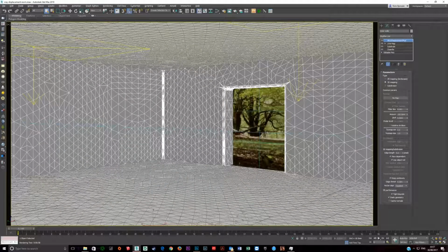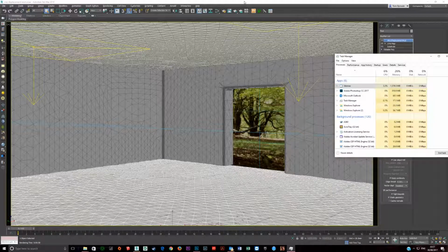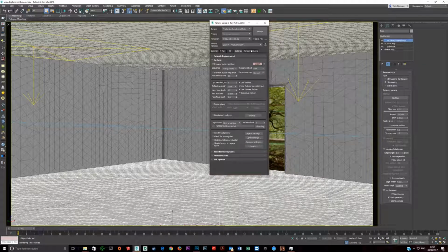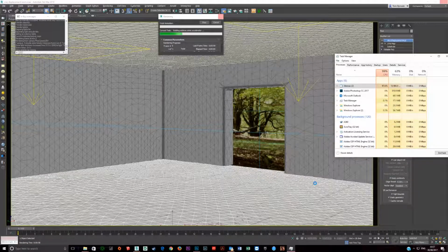I've got that region on, I'm going to click on it, displacement modifier. I set that to 10, so that's coming up 10 mil. I'm going to change this to 3. Let's see how much more memory it uses. Now I'm worried the computer might crash. I've got Conserve Memory on, I've got Use Memory. This is possible with this set to 3. It's going to use an extra 10 gig or so of memory. It's possible it won't, but it's possible that it will.